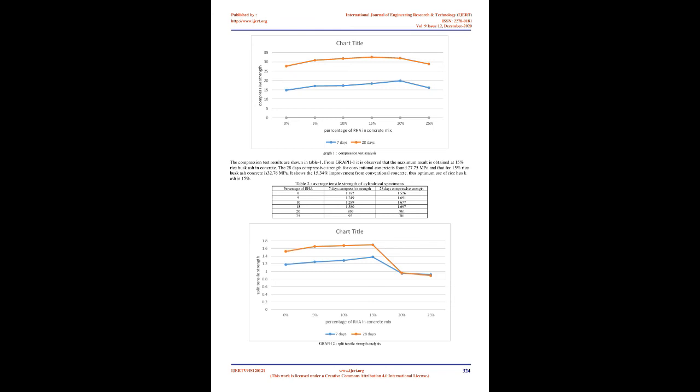Flexural strength. The beams of size 100 mm times 100 mm times 500 mm were cast for this test and the 1-point loading method is adopted for testing. Tests are performed as per ASTM C293. The tests are performed at 7 and 28 days.